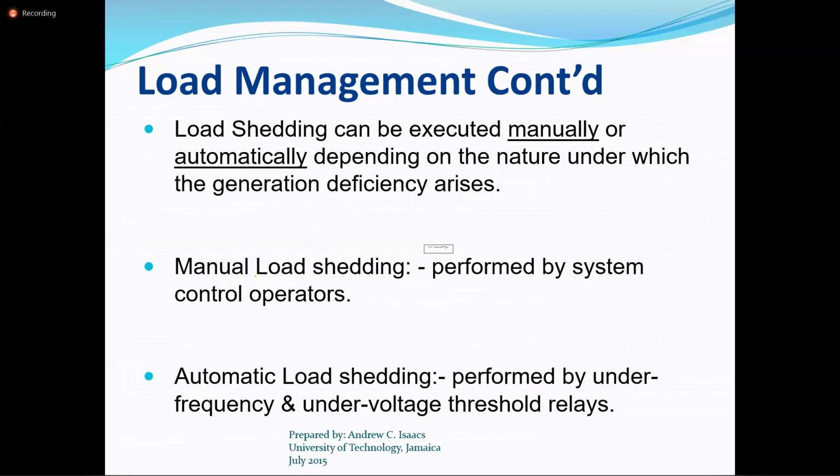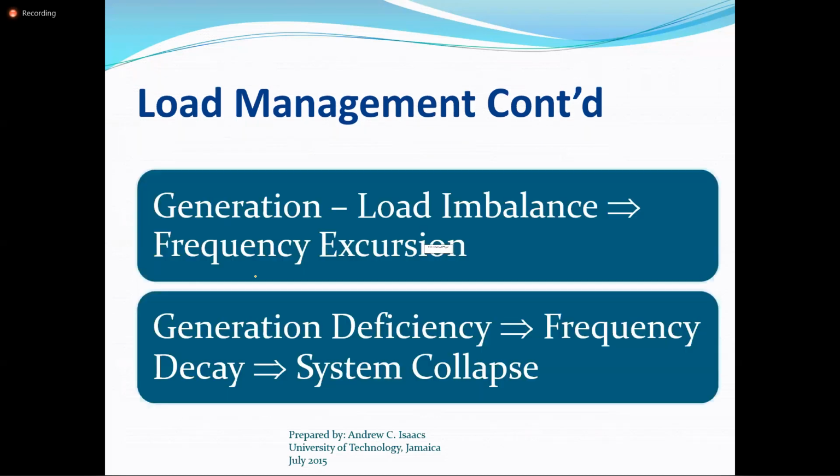So you can have load shedding by virtue of that happening, or you can have the generators themselves pulling out of the system. So you have the frequency issues when generation is less than your load, and that can result in the system collapsing.